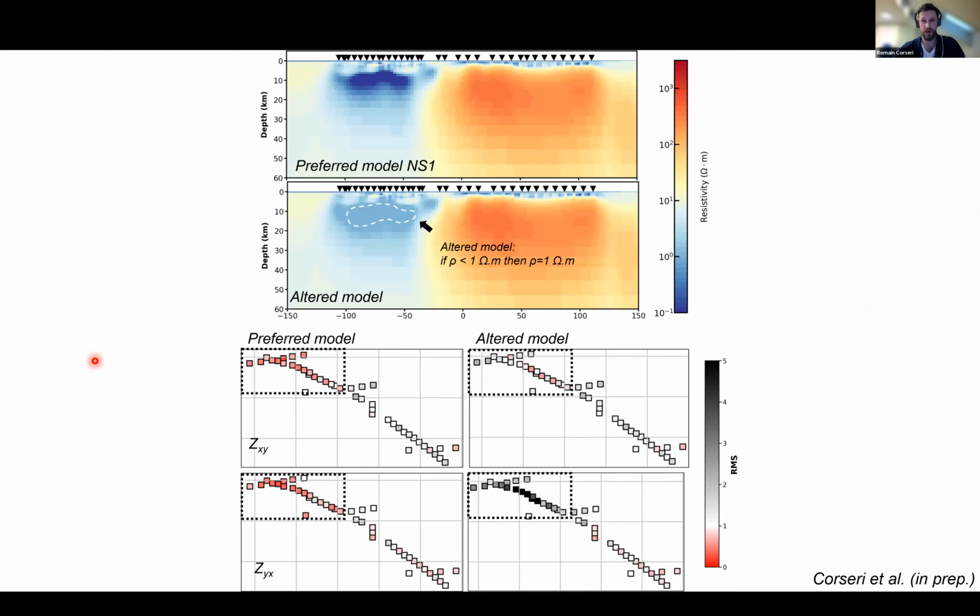Of course, when we have our electrical resistivity model, we have to test it for robustness. Are the anomalies that we are recovering real? Are they artifacts of the inversion? So we took every one of these prominent features that we've described earlier and ran them through a procedure called hypothesis testing. You can see one example here for the basin conductor. We erased all the resistivity below 1 meter in the anomaly, and we ran a forward model to see how the RMS is affected by the removal of this anomaly.